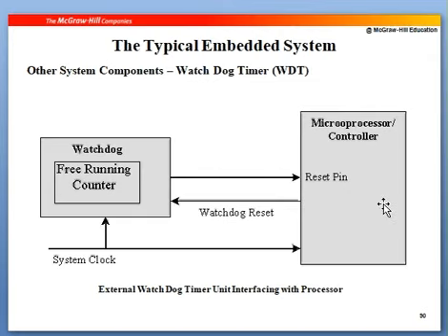There are a couple of registers associated with the watchdog timer, and those registers should be used to enable the watchdog timer and to introduce a value into the watchdog register. That is the time after which you have to pass a signal to the microprocessor to reset it, suppose the computer is hanged due to firmware issues.